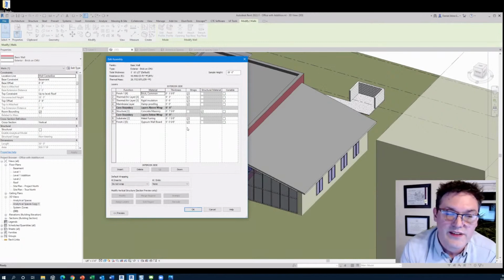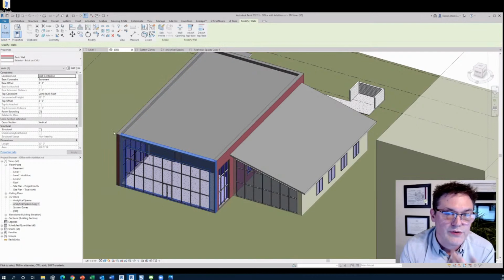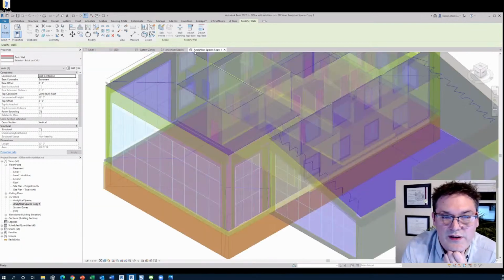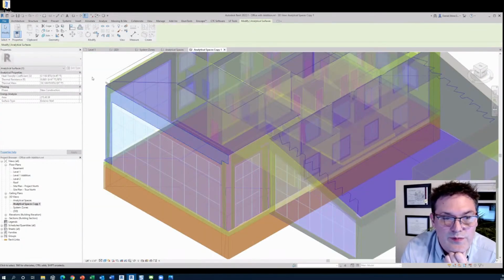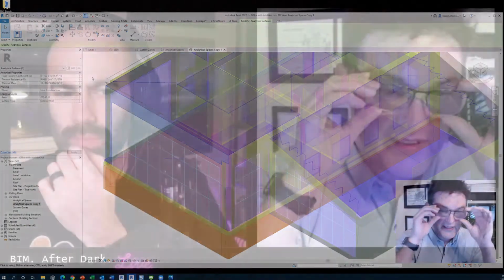So that retains and then releases heat in a specific way, and that's accounted for here. And all of this stuff then is plugged into DOE 2.2 or EnergyPlus, which are industry standard energy modeling engines. I'm actually writing a blog post right now for Lake Flato's blog, comparing a Revit plus Insight analysis that we did to Rhino and Climate Studio, just to show that if you have the same inputs, you should expect to get the same results.